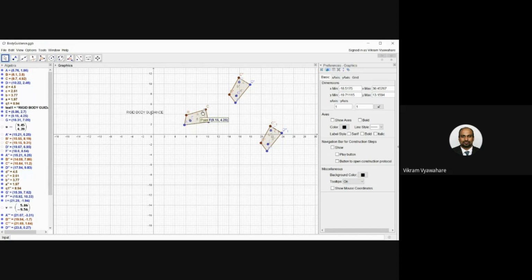There is a coupler motion, so the coupler will have at least two locations where you do the joint, right? There will be joints at these two locations, let us say. So we consider 2 points, and then you draw the same 2 points in the three orientations, whatever the three orientations. So the first step would be that.